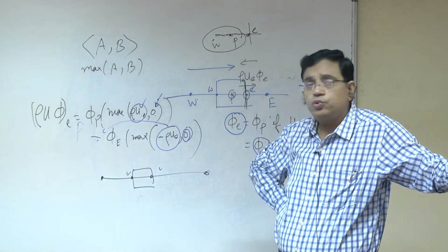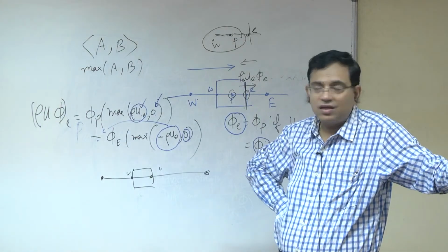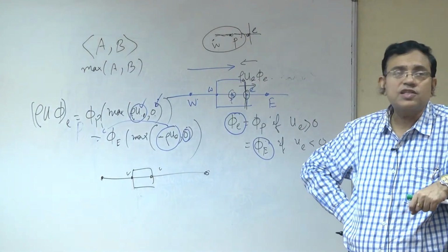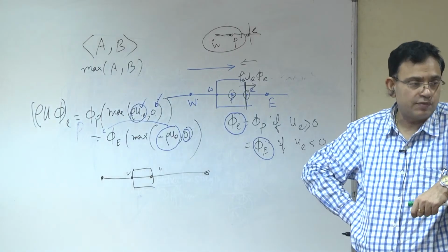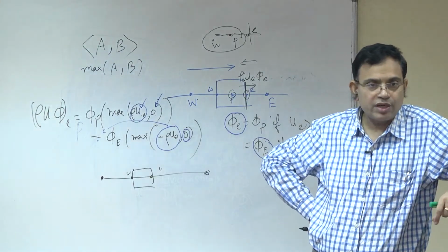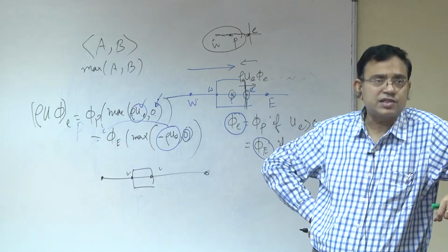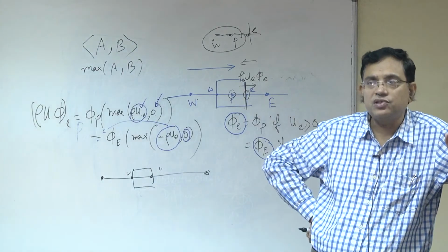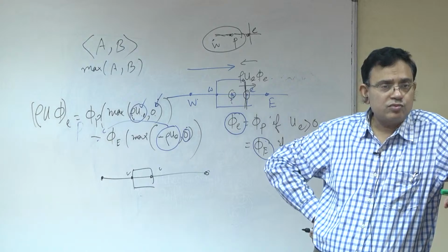In fact, if this is put into your left hand side phi small e and phi small w, and then it is integrated, you will get some discretized form, but people will usually not like to do it because you have exponential calculations, and exponential calculation, that is e to the power calculation, in computation is quite expensive, because you have to calculate a large number of terms of the exponential series e to the power x. So, this is always a golden rule for computation, that we should try to avoid such exponential calculation. Another challenge with exponential calculation is that if the argument of e to the power is large, then the exponential can blow up numerically. So, that is the so called exponential scheme.